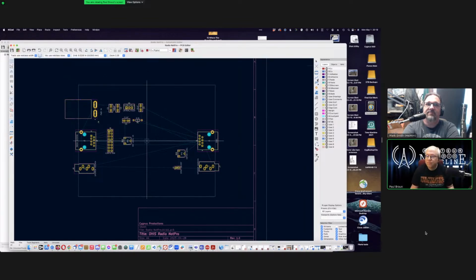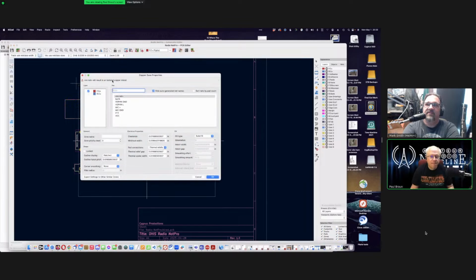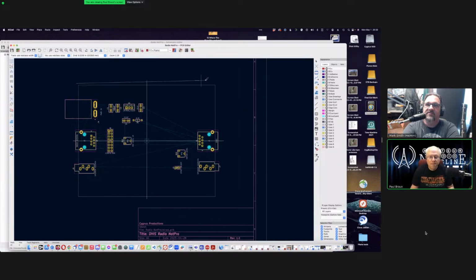Command S, I should say, because you're a Mac user. And I just draw outside the whole box, right? Sure. Nope, you got to do points, because that still does a selection. Do front and back. And select your net, earth. Make it the earth net, because that's our shield. So this is going to be a shield around everything.